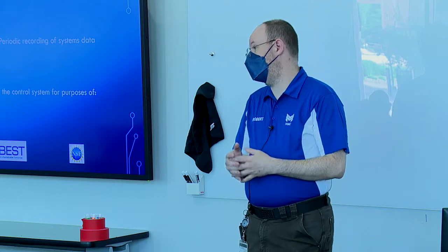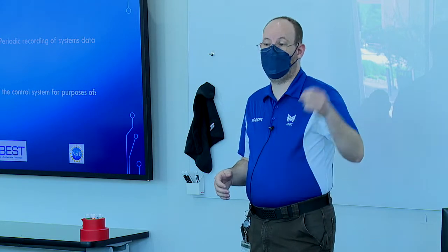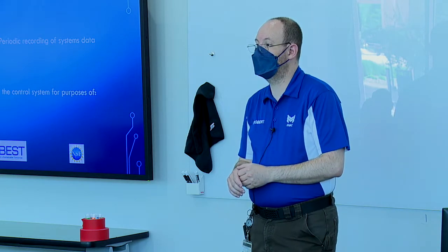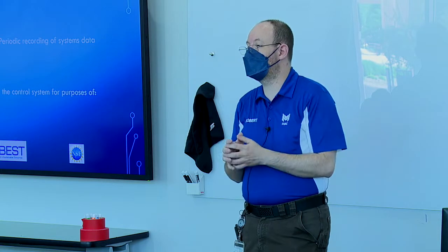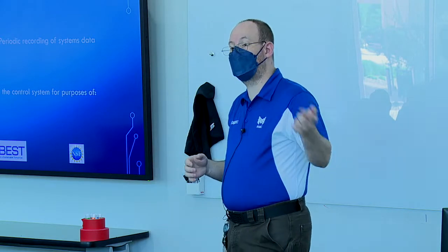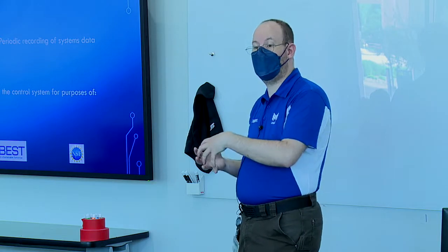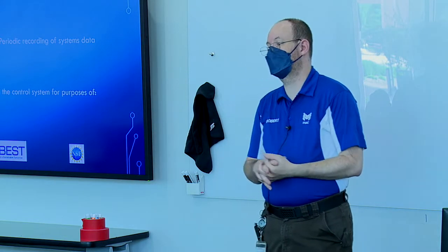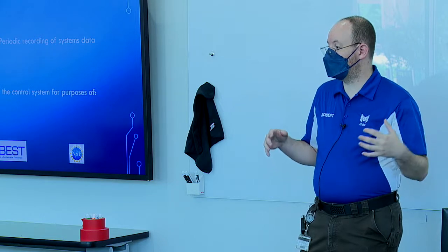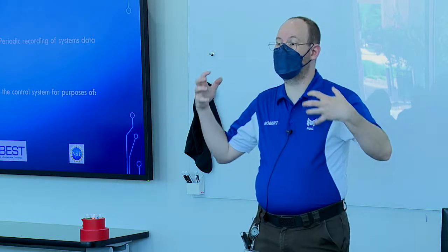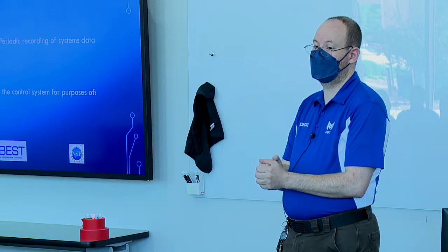And if you notice patterns in those logs, every Monday morning, my low limit trips, if it's below 20 degrees outside, on air handler 1, that's a historic problem. You can start predicting that problem. You can start addressing, okay, now we need to find out why that's happening. Histories and logs are a huge diagnostic tool.